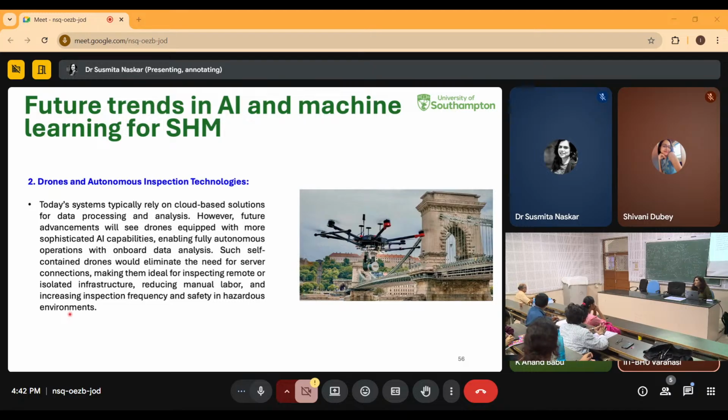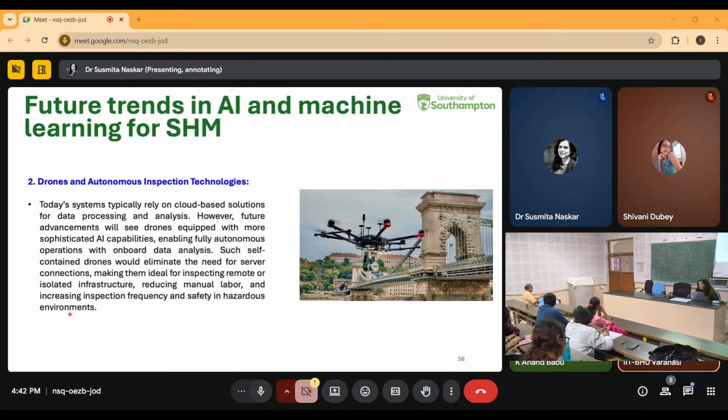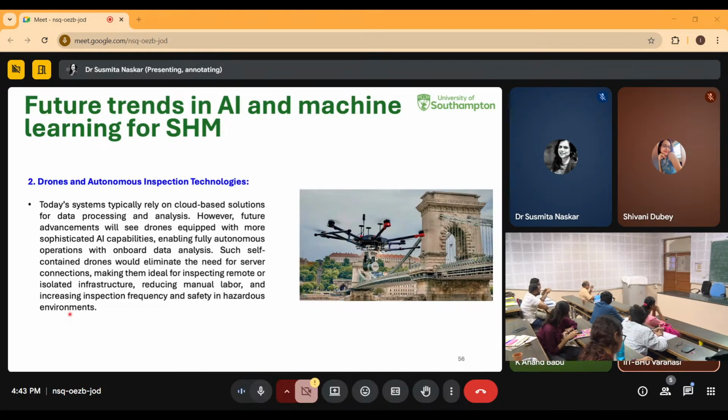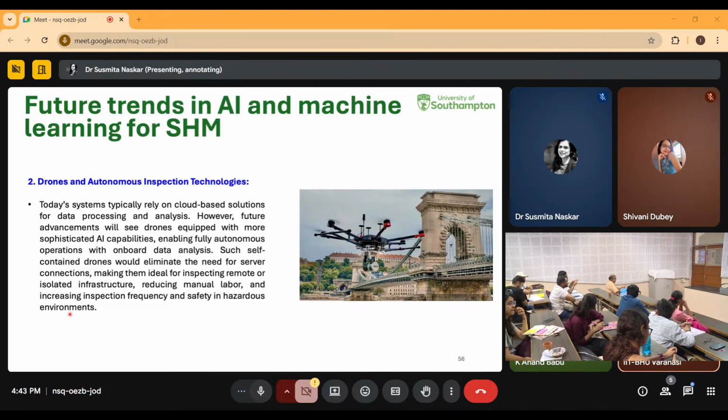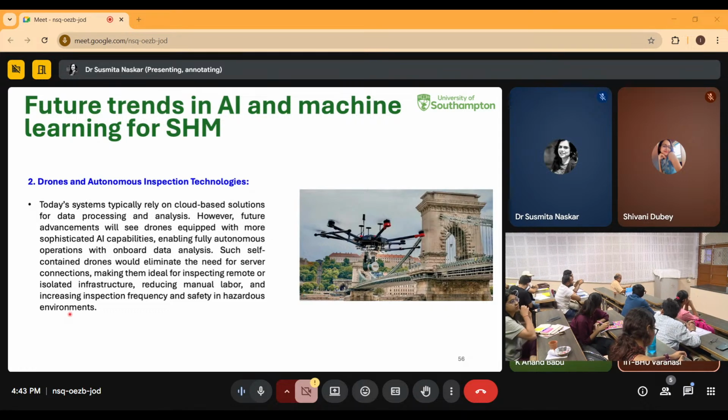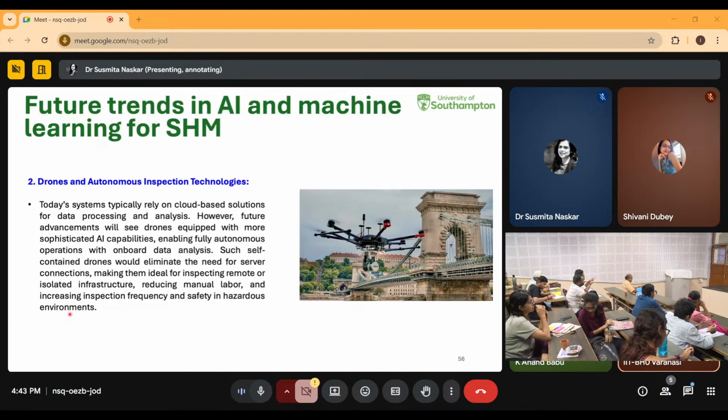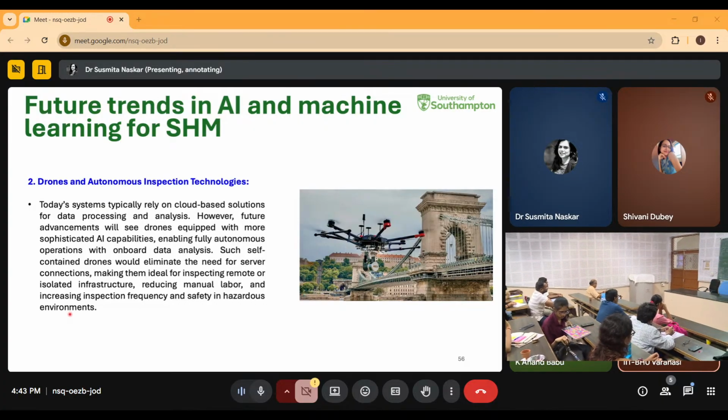I think this is why, when we are developing some AI technology, we train the AI based on the history of one particular structure, and we give the response to the AI and the physics as well, and based on the response and the earthquake data, we train it. That AI is only able to predict the response and generate results for that particular structure. Because if the structure changes, the mass matrix, stiffness and all those things change, so we cannot define one model for any other structure.